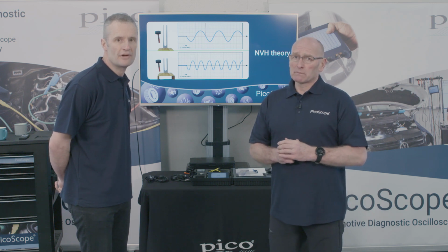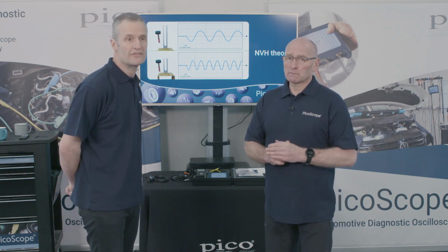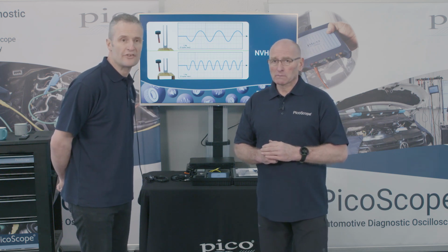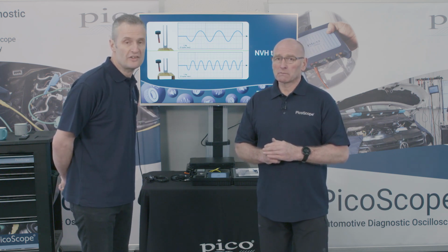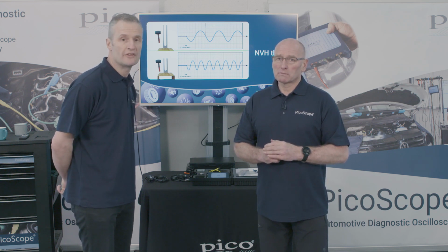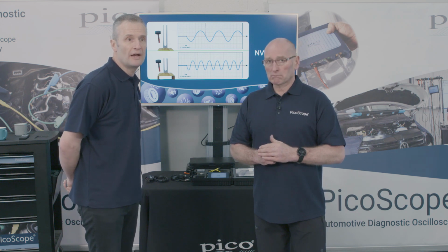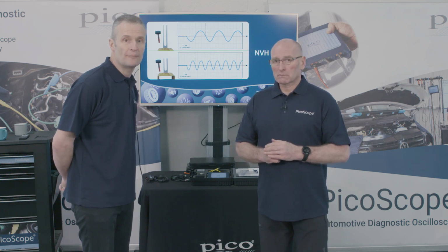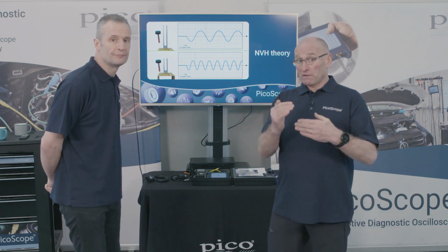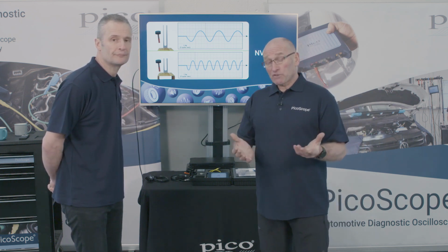Yeah, certainly during the road test, during a customer interview, let's set that vehicle up exactly how the customer drives: customer settings, mode settings, sport, the active damping, ride height. All of this will affect the cabin from a noise vibration point of view. And we also have now a higher level of technology. We have active noise control.